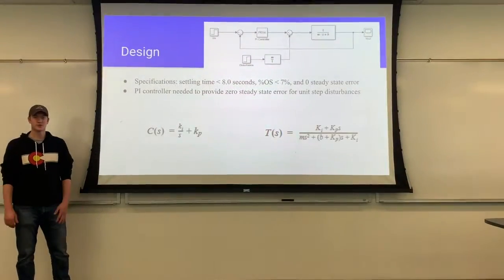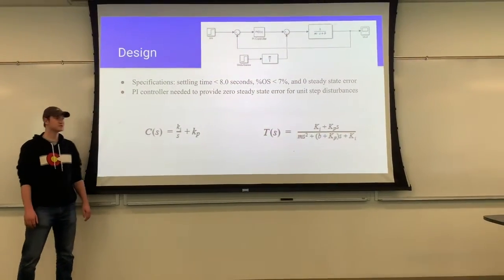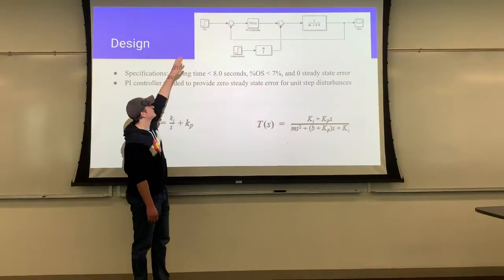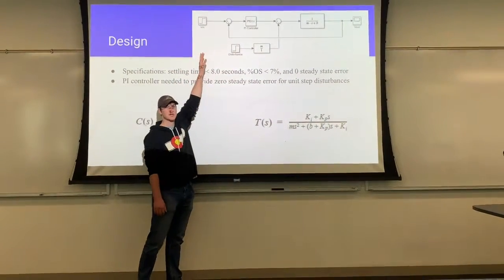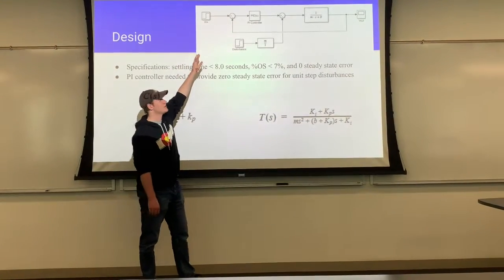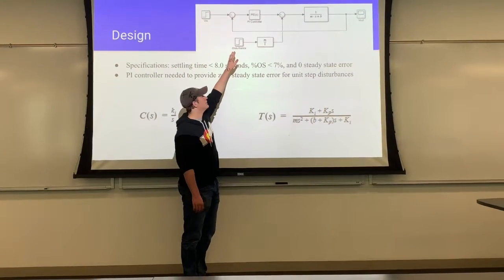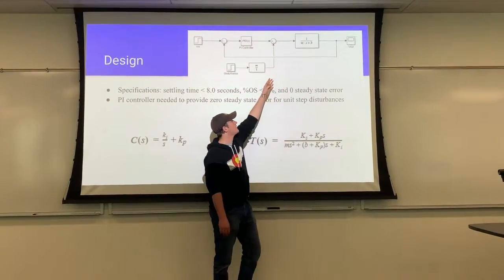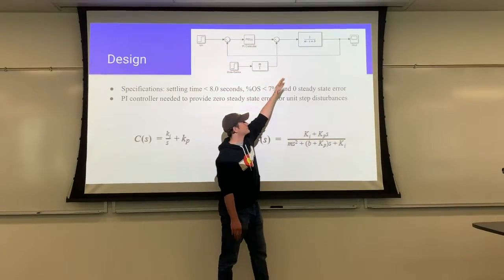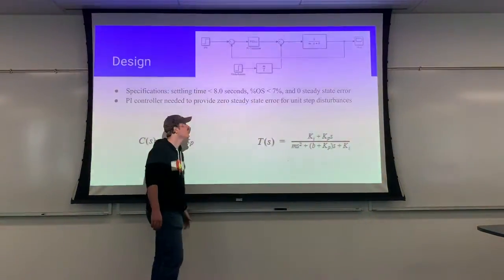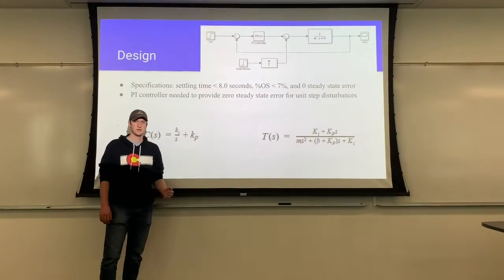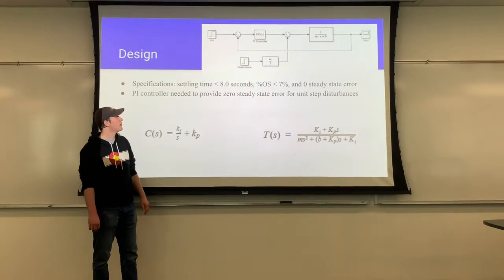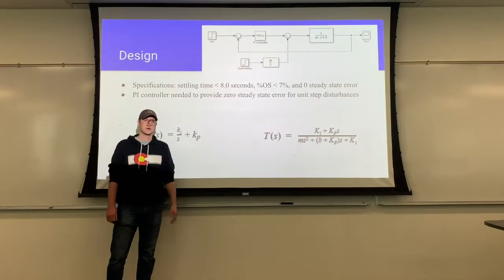My name is Matthew Sieler, and I worked on the design portion of this project. For the design, we modeled our closed loop system in Simulink. We have our velocity in represented as a step input that goes to the velocity the user set, which will lead to a controller that I'll talk about in a second, which will lead to our plant system dynamics, which will result in a velocity out. We need to account for disturbance as the road will be inclined and declined. We represent disturbance as a unit step input, which will be based on the degree of inclination on the road.